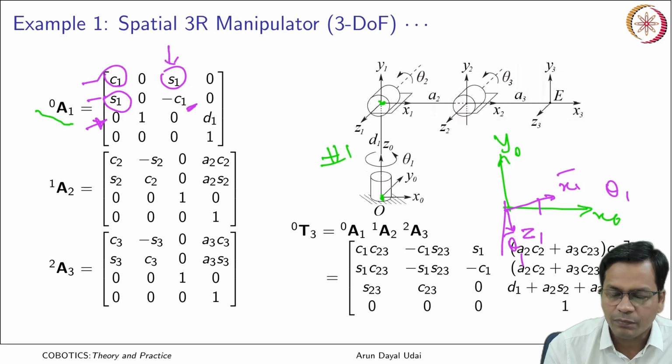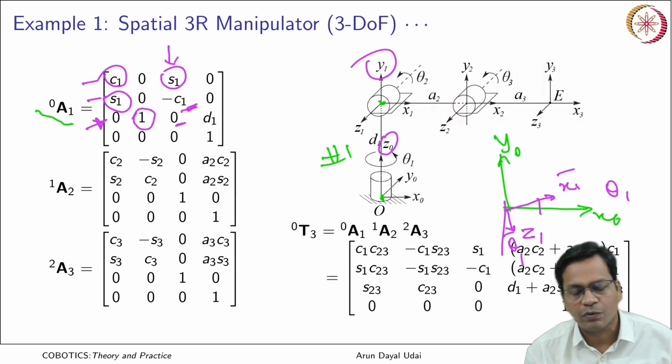Mind it, all the vectors here, x0, y0, z0, x1, y1, z1, are all unit vectors. So this is here, and then finally it is in a plane, so that makes it 0. What about the z axis? Okay, z axis projections. Along z0, y1 is always lying, so you see a continuous projection of y along z as 1, and the other two projections become equal to 0.